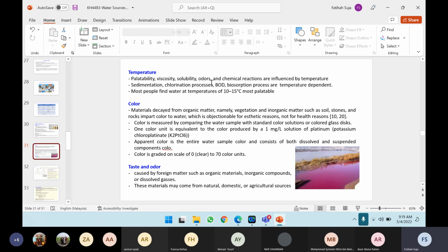This one is harmful to humans and also to aquatic organisms. So this is why temperature matters, because sometimes the ammonia is there and the ambient temperature is okay, but suddenly there is flow from industry into the rivers, which has high temperature, and it will increase the temperature of the water body and affect the chemical reaction of the ammonia present in the existing water body.